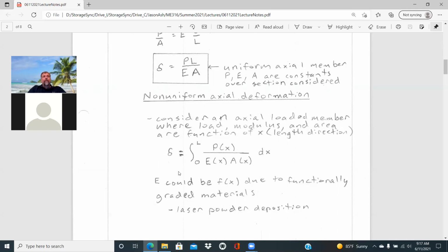When you are generally dealing with segments, if you have segments of different materials, those really can be looked at from each individual member separately, and then looking typically at the compatibility. One is going to want to maybe stretch more than the other. They're kind of working against one another. And so based on the Young's modulus of the two materials, where is that equilibrium point where equilibrium is satisfied?